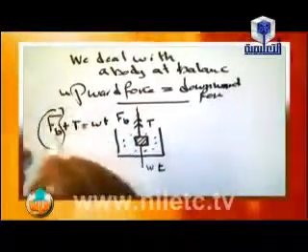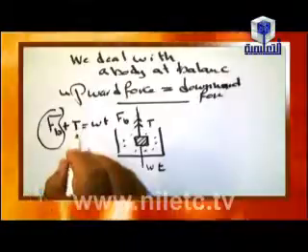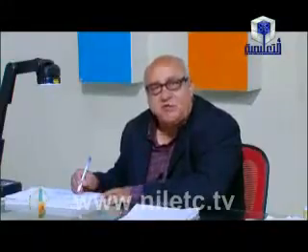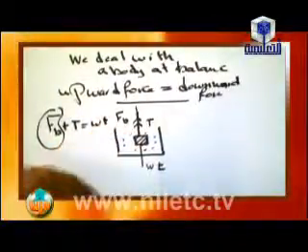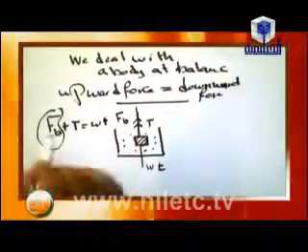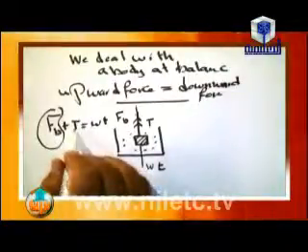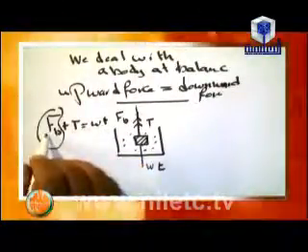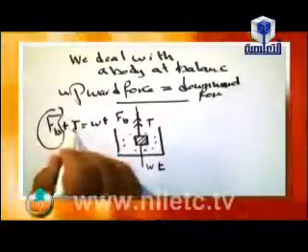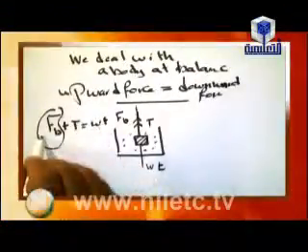What is the rule of FB? The body in this case is wholly immersed. So FB is equal to rho V g: rho liquid times volume of the body times gravity. And we can find the tension, and also we can find the weight. The problem gives you tension and weight to find FB, or to find tension by using weight and FB.